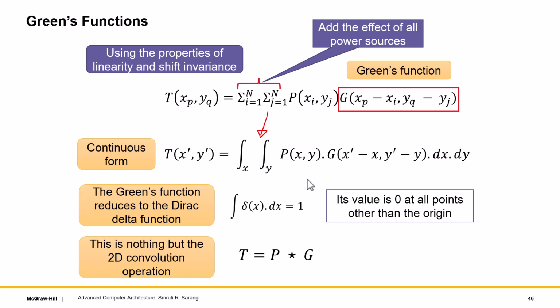So the moment we went from here to here, our power source started resembling this, which means that it became really, really small. It started resembling a Dirac delta function. The moment your power source becomes so small, so let me delete this, this part is not correct. The moment your power source becomes so small, the Green's function becomes the temperature profile of that ultra small power source.